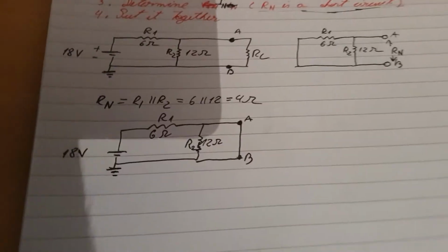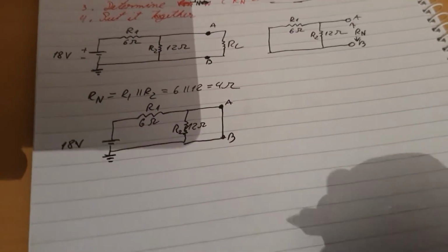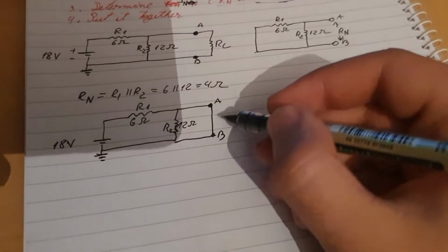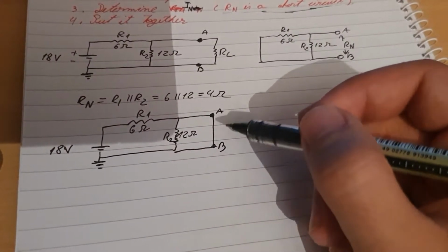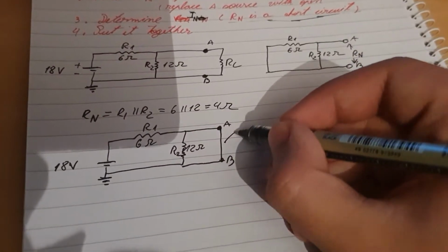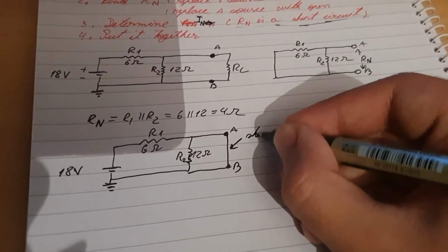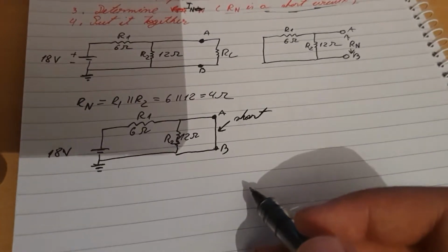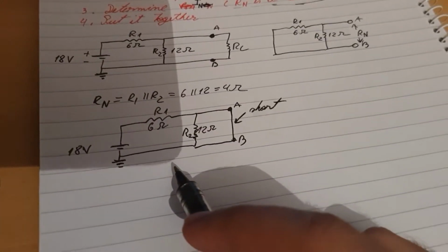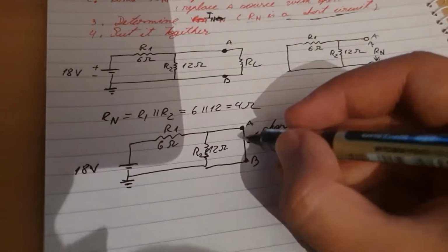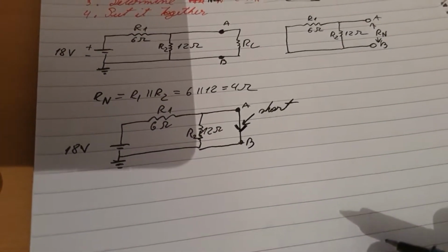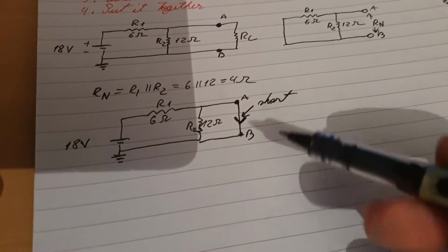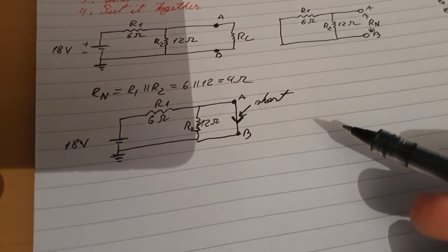Now you may say, did you draw the diagram wrong because there is a line in here, or do you ignore it? But no, this is an actual short. When you are calculating Norton, the current, you are calculating the current going through this wire, and because it's a short, this will become a shortcut for a lot of circuits.